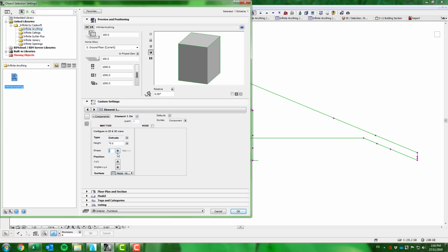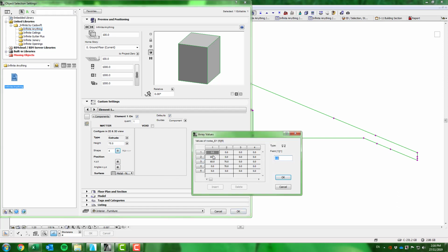Best to do this in 2D, but with a tabletop, something simple, you could actually set it in here. So these are your X and Y values. The ones after this you ignore. They're only relevant for computing other things, and they're automatically populated. So it's just these first two. So you can see here X, Y. So you could effectively, if you knew you were doing a 1200 by 2400 table, you could just do, say, minus 600, minus 1200, so that's half. So that's setting the table in the middle, obviously.